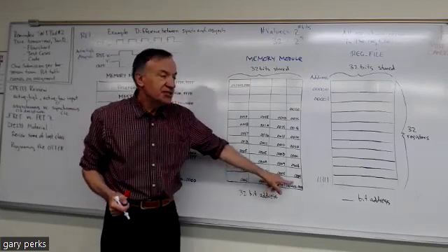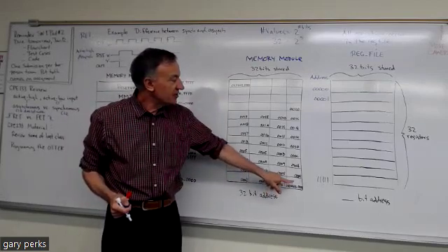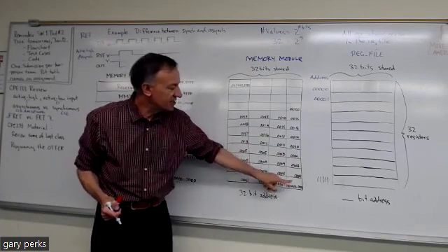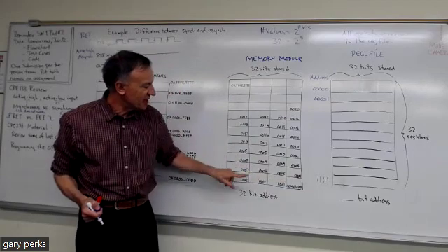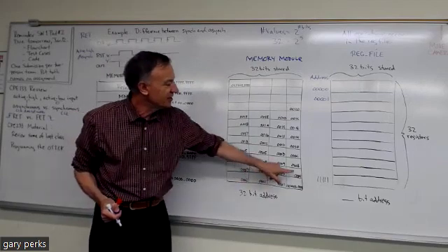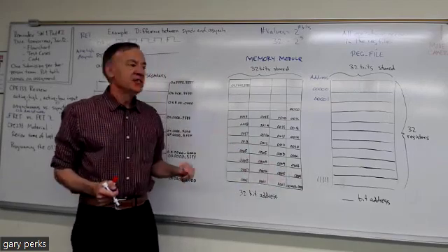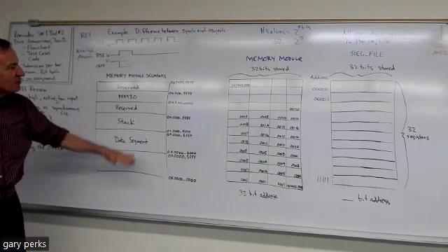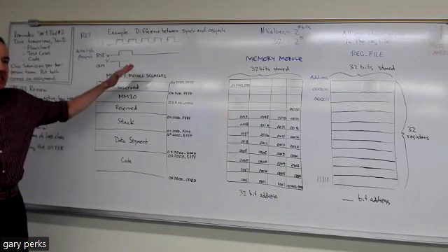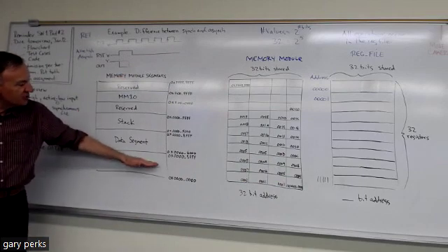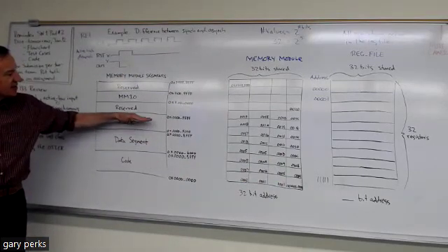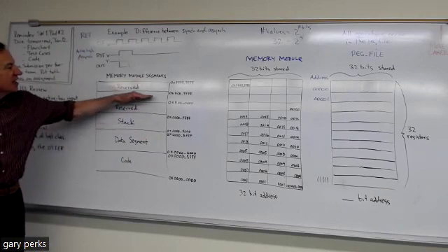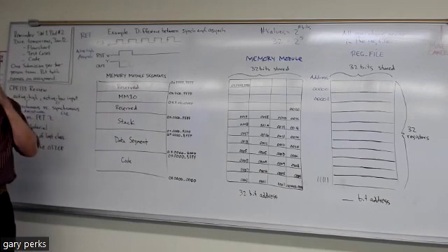So each 32-bit register in the memory module has 4 addresses, because each byte has an address, and so on, all the way up. Also, we talked about last time that the memory module is made out of segments. We have a code segment, a data segment, a stack segment, then there's some reserved segments which are not used, and then we have this memory mapped IO segment.